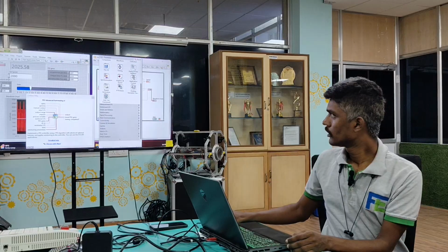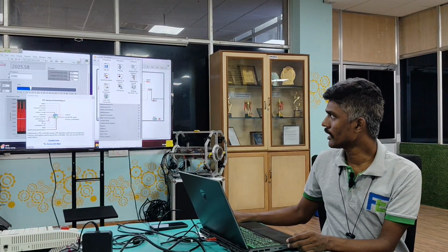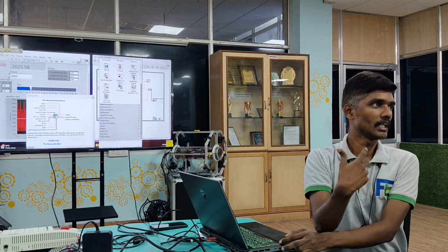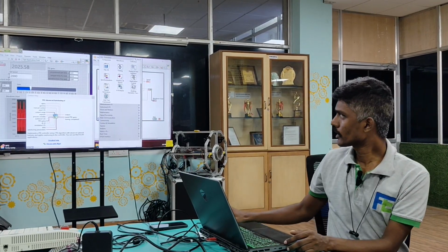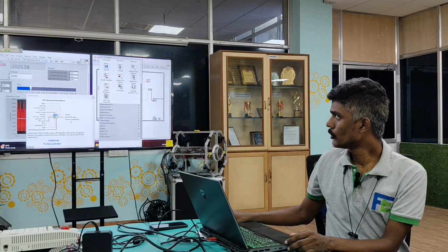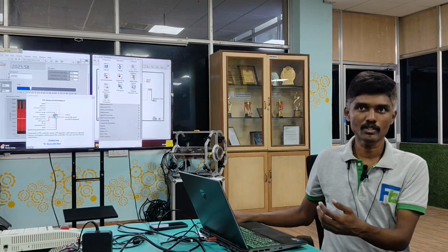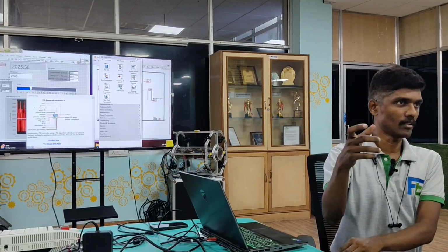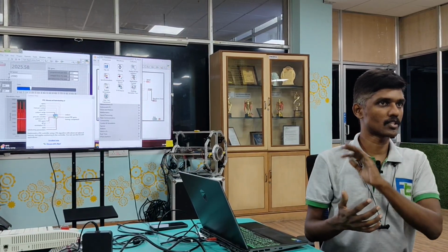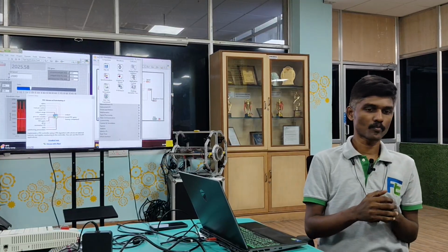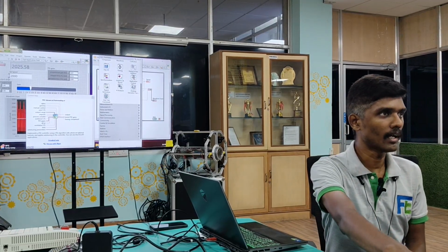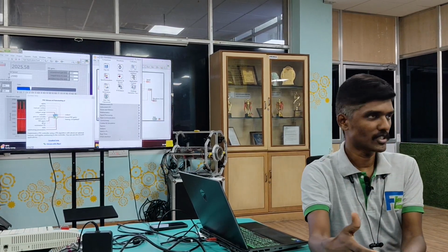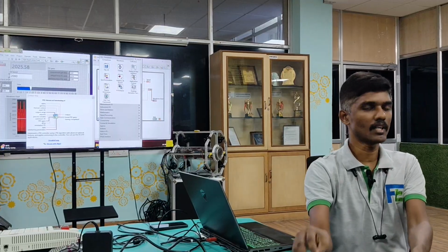So when you select this auto tune boolean button as true, depending upon your set points as well as the actual reference value, it will generate the gain values. Once you get the output as tuning is completed and tuned PID gain values are available, enter the same values in your PID gains manually or using local variables, then your system will run normally with the tuned values. So now I have one DC motor. This motor speed I am going to vary by adjusting my voltage. We will measure the speed and tune the same system in the hardware part.